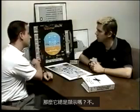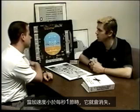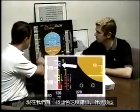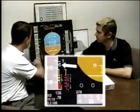Okay. Is that always displayed then? No, it'll display anytime acceleration is greater than 2 knots per second, and it disappears when acceleration is less than 1 knot per second. Now we have a blue speed bug. What type of speed is that? That's a selected speed.